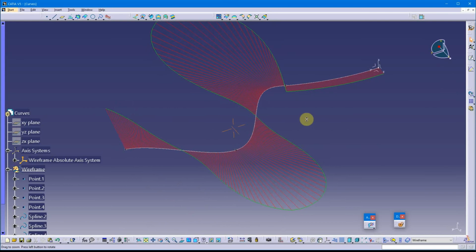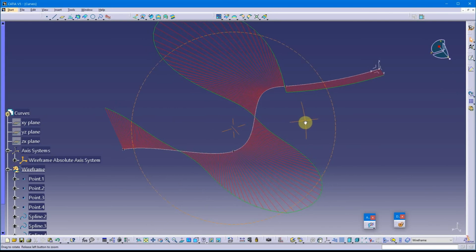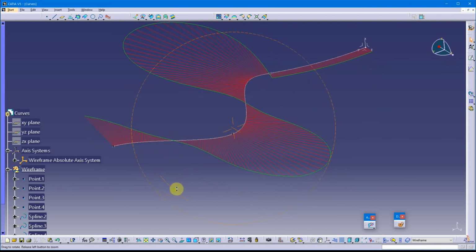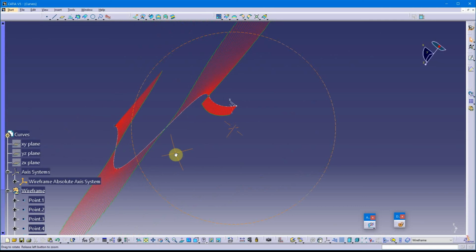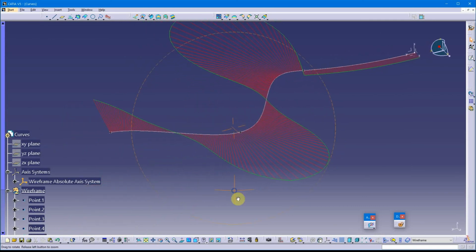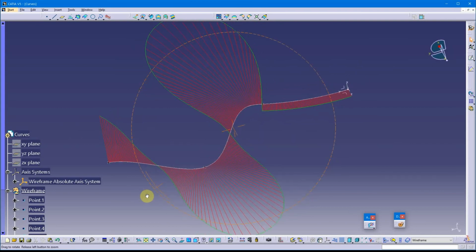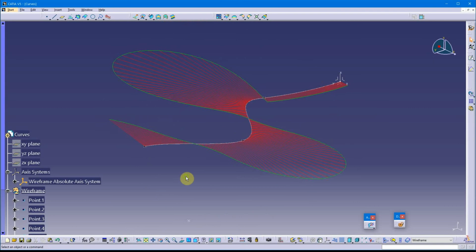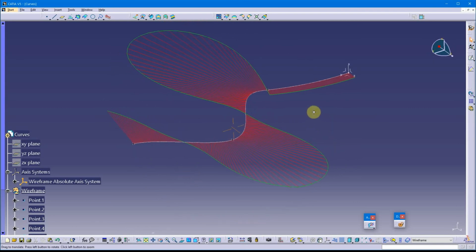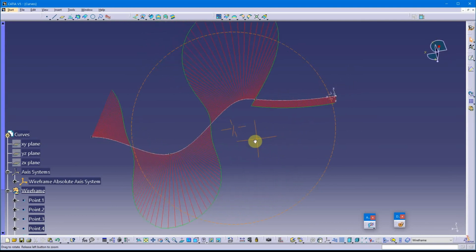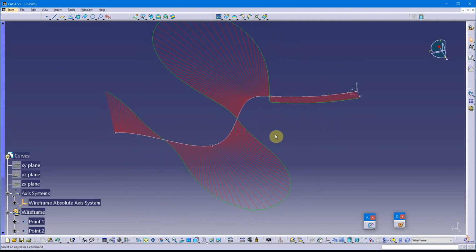You could have products where reflections are not quite as important, such as maybe power tools. So you may have a company that says, hey, we want G1 or better to be our Class A surfaces. So it's really based on a company, but the automotive industry typically will use G2. Now you can actually go up to G3 for styling surfaces, NURBS-based surfaces, but CATIA's GSD workbench for the most part stops at G2. I can replicate G3 by manipulating the tension tool, but that's another topic for another day.